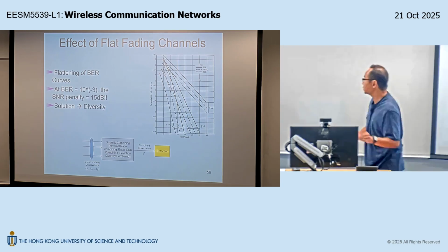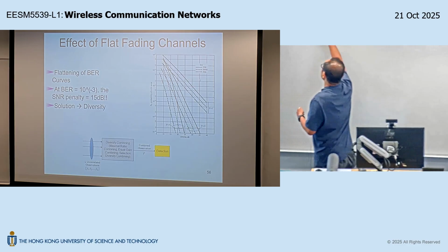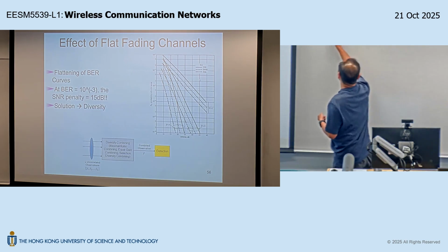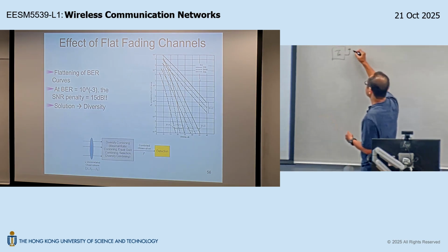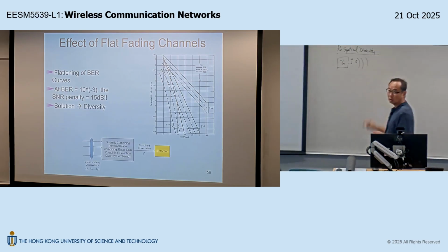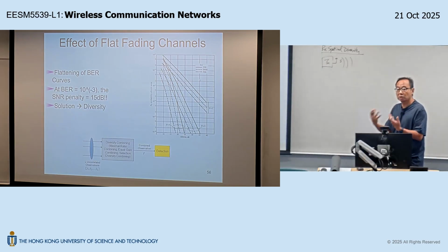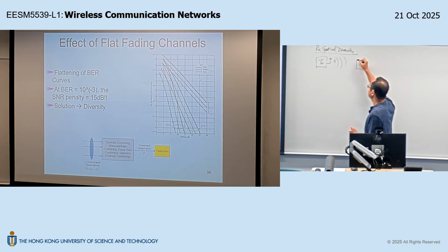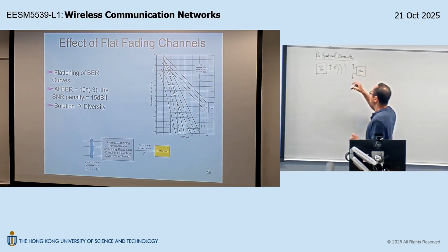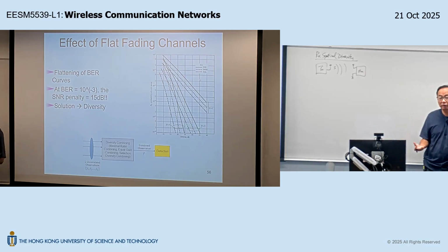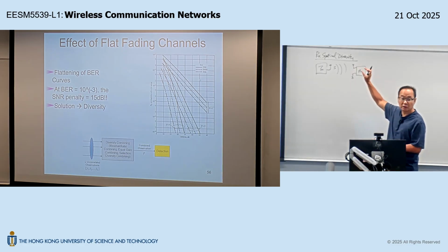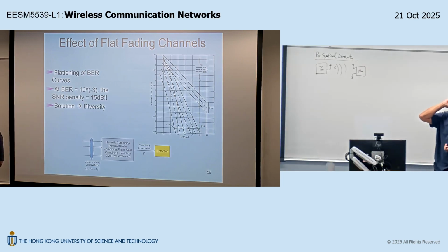With receive spatial diversity, the transmitter just transmits the same information, the same symbol, once. It just makes use of the channel one time to send one symbol, right? And then the receiver, having multiple receive antennas, will be able to pick up multiple observations about the transmission. And these multiple observations will suffer from independent fadings if the separation of the two antennas is sufficiently large, right? And then we talked about how large is sufficiently large.